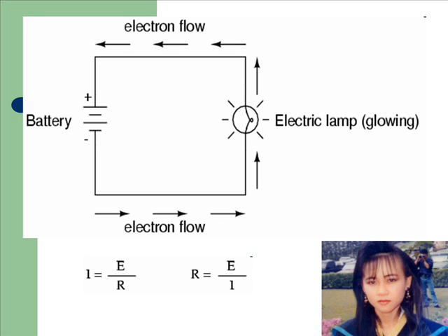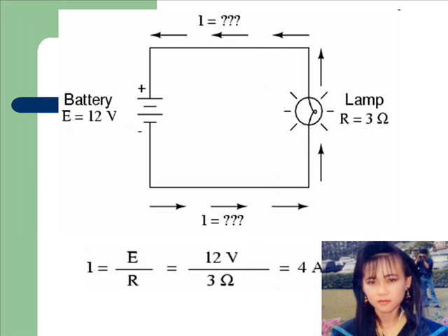In the above circuit, there is only one source of voltage, the battery, on the left, and only one source of resistance to current, the lamp, on the right. This makes it very easy to apply Ohm's law. If we know the values of any two of the three quantities, voltage, current, and resistance in this circuit, we can use Ohm's law to determine the third.